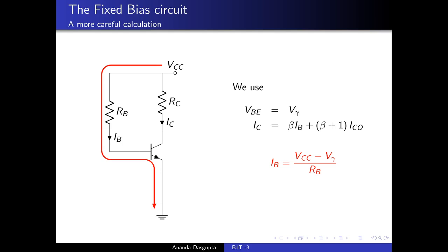The fact of the matter is, as far as transistor operation is concerned, it is VBE which actually does all the controlling. The base emitter forward bias dictates how many electrons will flow from the N-type emitter to the base, and then of course will get swept on along to the collector. Changing VBE will of course drastically change the currents.